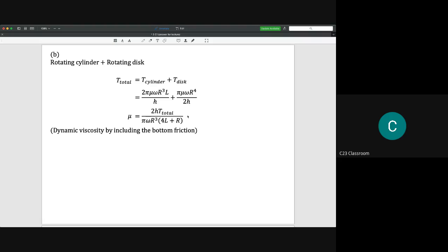But the manufacturer will calibrate the machine with a few oils or liquids, and then they will create a graph, and give some kind of coding, a program, to make sure that we could get the value of dynamic viscosity when the machine supplies a certain value on top.